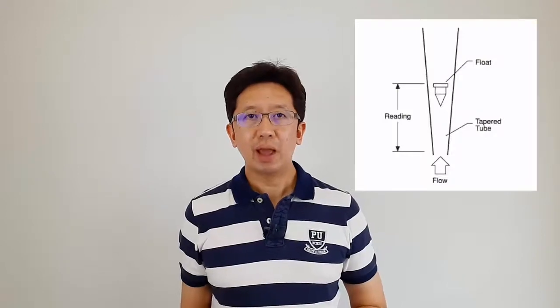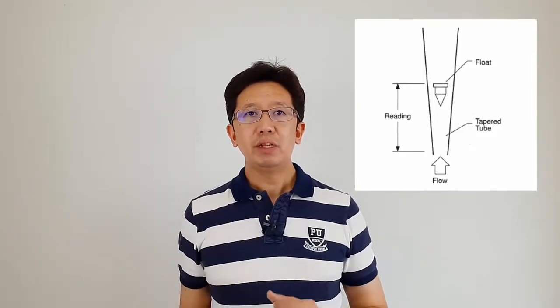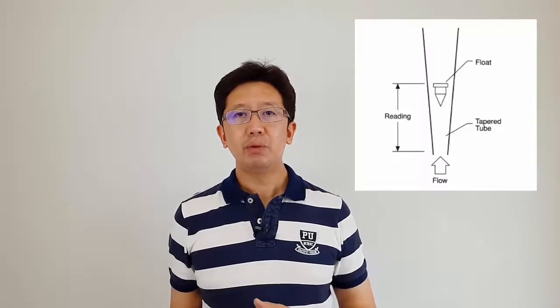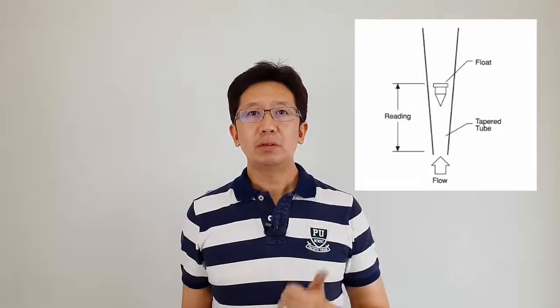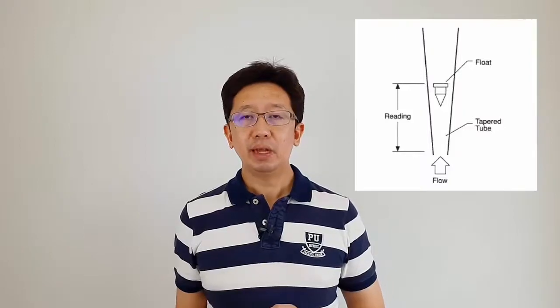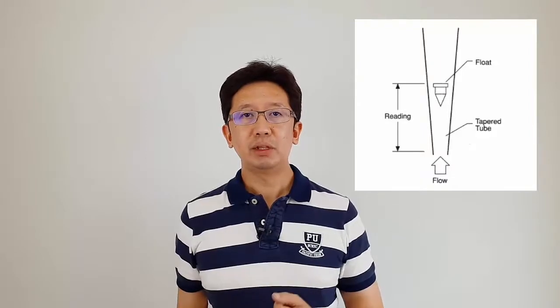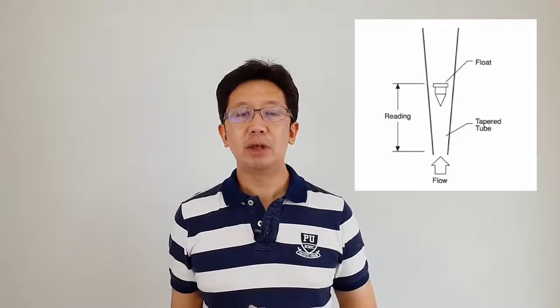Next type is variable area. Variable area flow meters are widely used for small flow rate measurement, such as in laboratory rooms and general industry. The benefits of the variable area flow meter are low cost, low maintenance, low pressure loss, direct flow indication without requiring any power supply, and the ability to detect very low rates of both gas and liquid, including viscous fluid. The limitation of the variable area flow meter is that the transmitter accuracy is relatively low, and it requires installing in only the vertical direction.